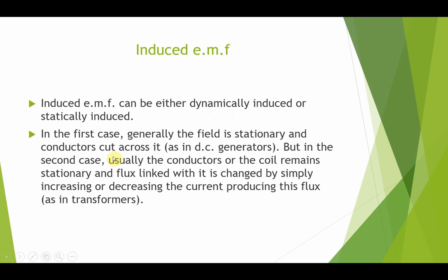In the second case, the conductor or the coil is stationary and the flux linkage with it is changed by simply increasing or decreasing the current producing this flux, as in a transformer. In dynamically induced EMF, the field or the magnet is stationary and the conductor is moving.